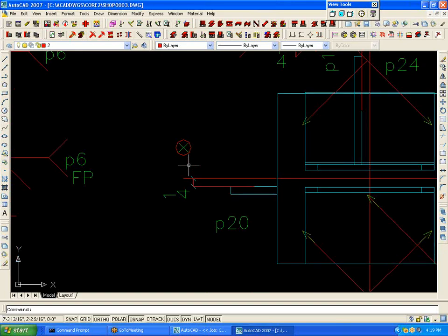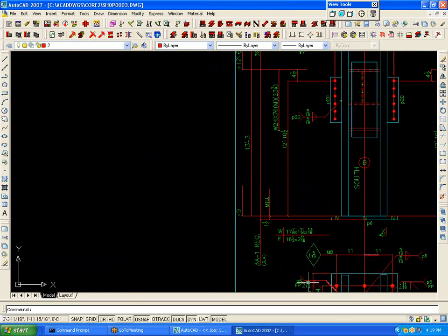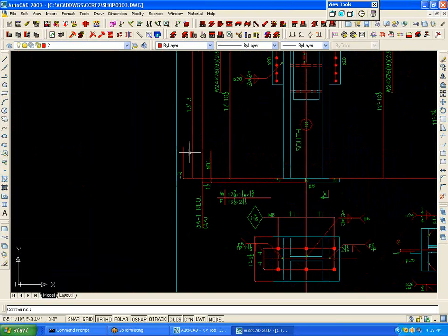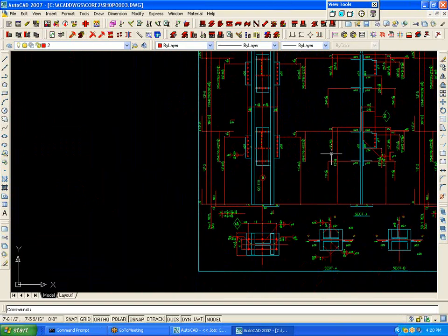This little round thing with the X in it's the target mark, so they know in the field which side the strike face is. They put a little X or a strike mark on the plate in the shop. There's your offset for checking. There's your grid line location. There's the information the checker needs, and the extension dimension is what the shop needs.